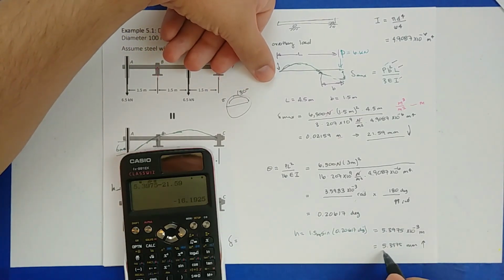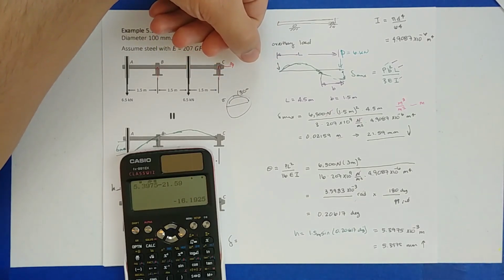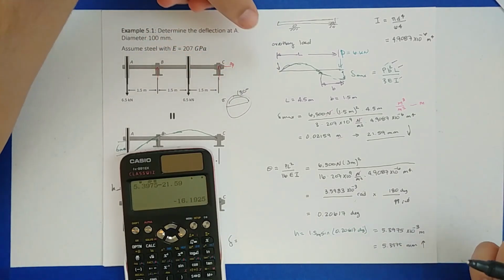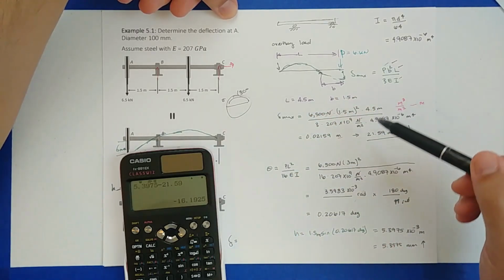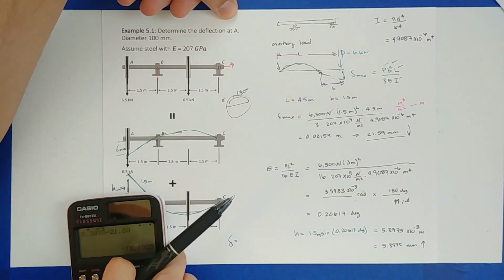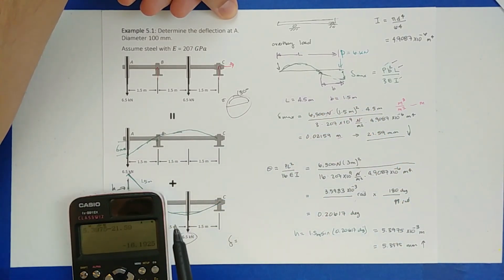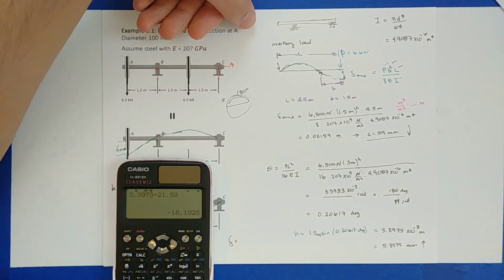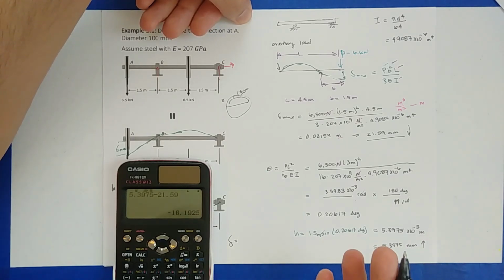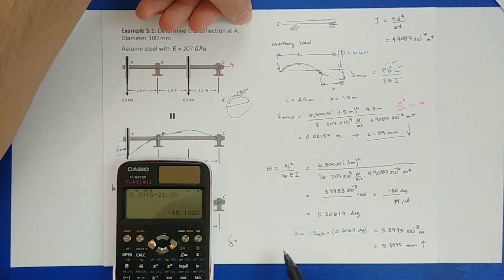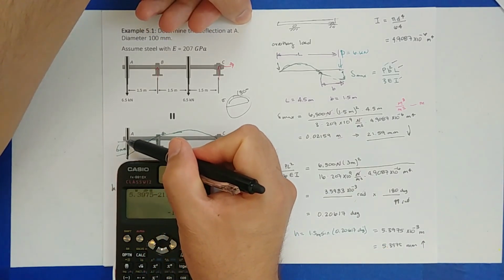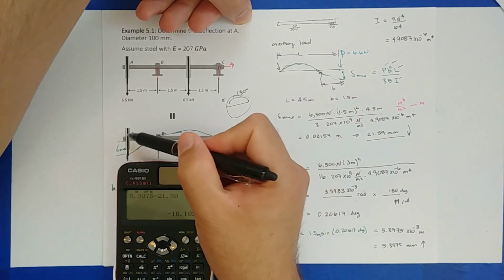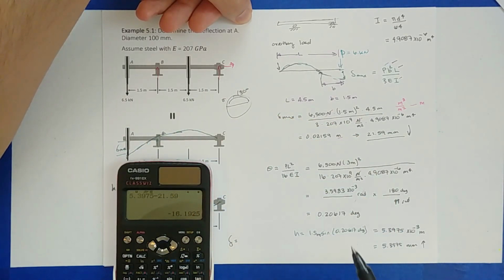Again, what did I do? Since this one is up, in this class, I know when you go through solids, sometimes they tell you for a beam that has a loading downwards, then the deflection downward is a positive deflection, and it gets all confusing. For the homework assignments for this class, we're just going to say, look, if a deflection is down, it'll be negative. If a deflection is up, then it's positive, right?